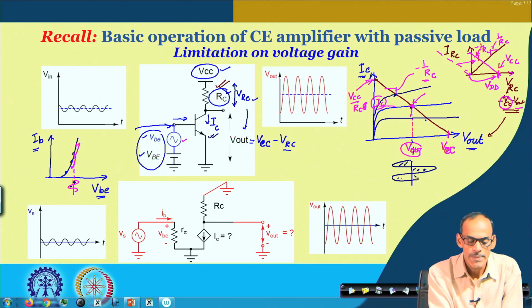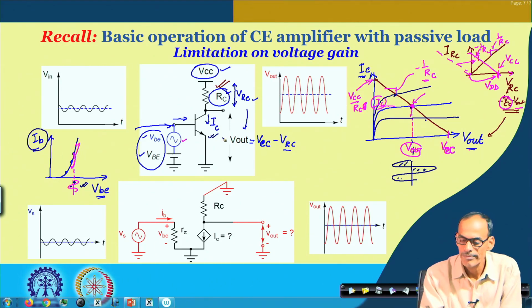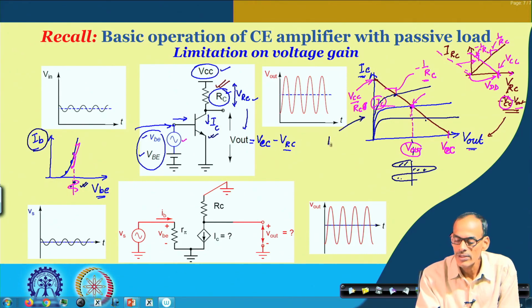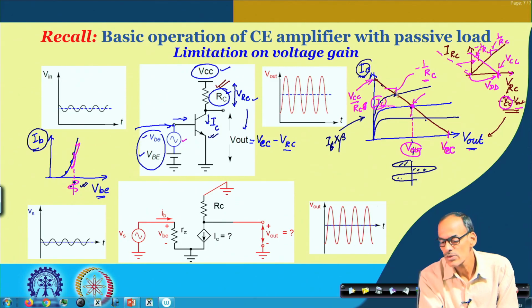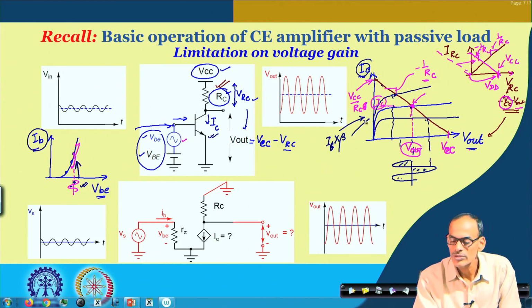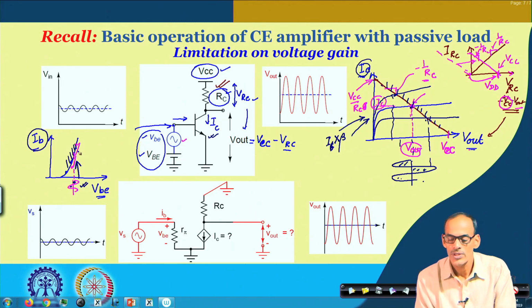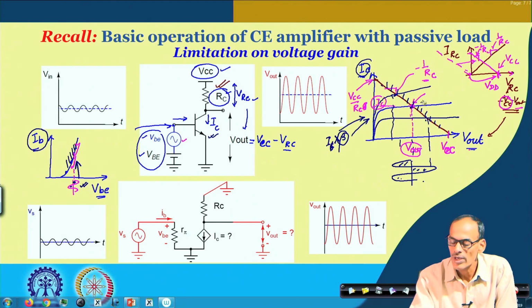Now, the gain, starting from the input, gets converted into current IB, and then through multiplication by beta we obtain IC. Then, by this load line, the signal part gets converted back into voltage. So, we have a voltage converted into current, this current comes to the y axis, and the load line characteristic converts the current back into voltage. So, we can say that we have two reflectors: one is the IB versus VB characteristic reflector multiplied by beta, and then the other reflector.